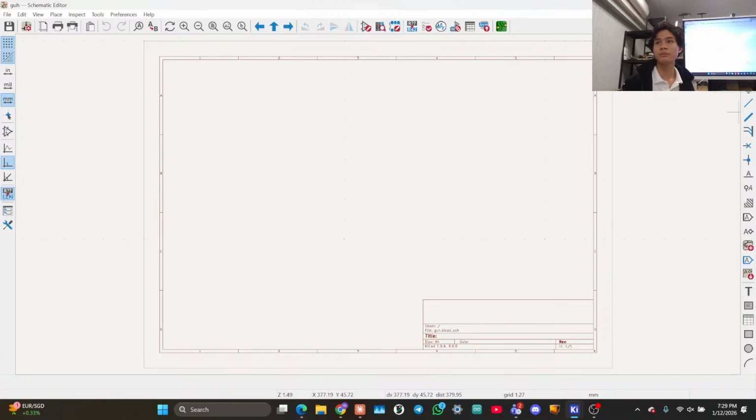For now let's go straight into symbols. This is highlight nets. Nets are a key concept in PCB design software. A net is a set of positions which are connected together electrically. This means you have this set of points in your circuit which are all considered to be connected by ideal wires. Later I'll show you that you don't need to wire something together, you can just make them part of the same net, and this makes your circuit way cleaner. The moment you have more than about 50 wires, everything goes to hell. It's much easier to use nets for everything.